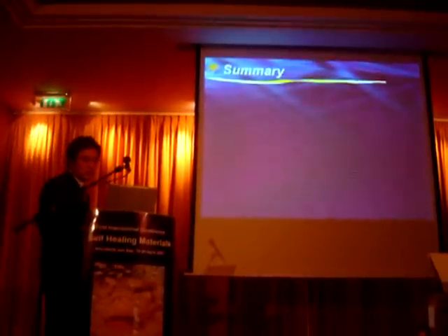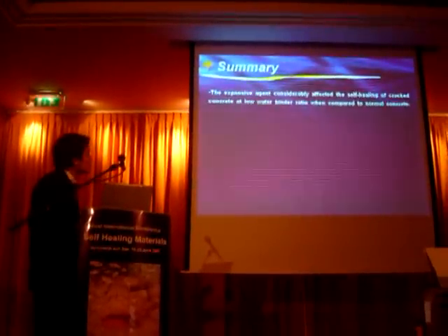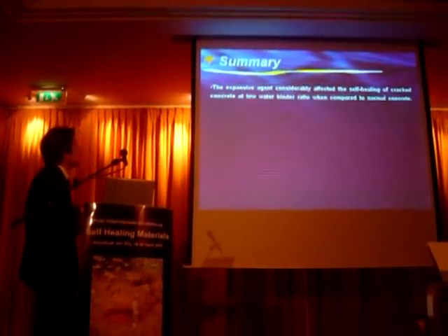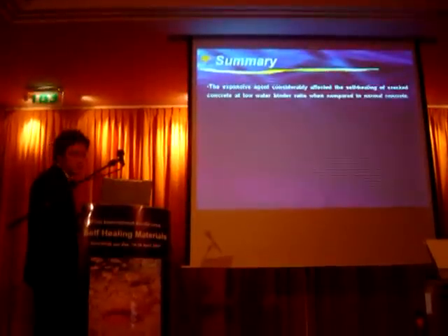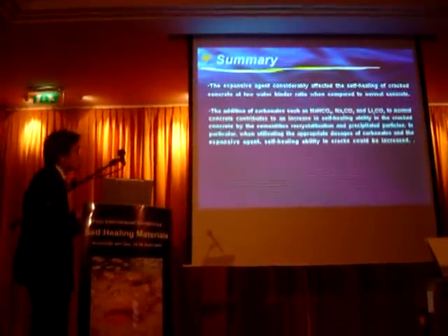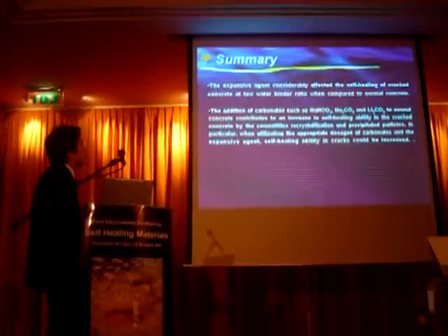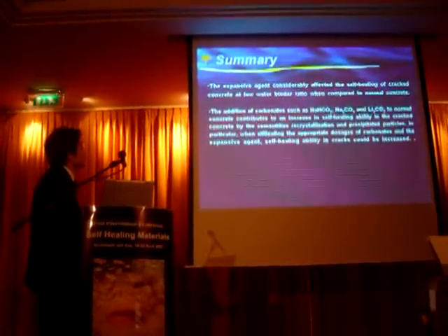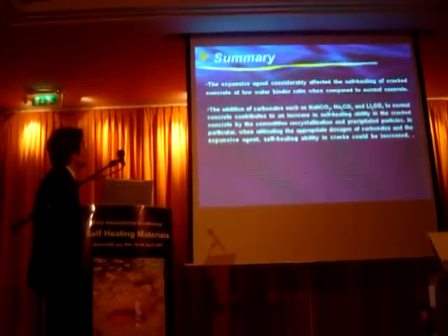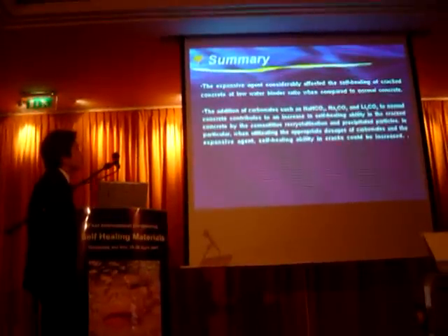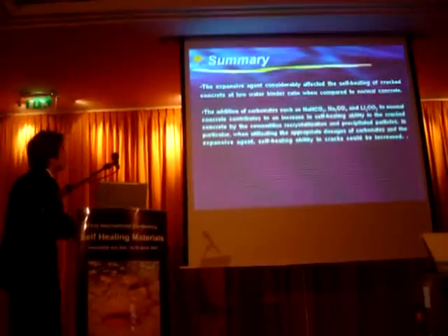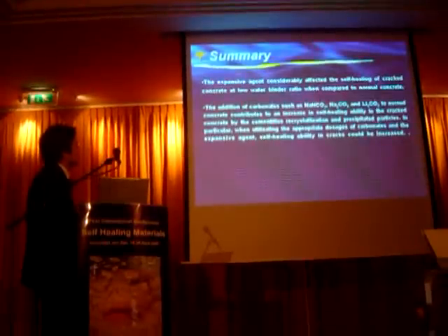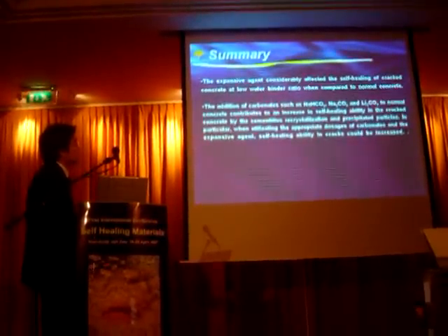So the summary of my talk is as follows. First, the expansive agent considerably affects the healing of cracked concrete at low water-binder ratio when compared to normal concrete. Secondly, the addition of carbonates, such as sodium hydroxycarbonate, sodium carbonate and lithium carbonate, to normal concrete contributes to the increase in healing ability in cracked concrete by cementitious recrystallization and precipitation particles. In particular, when utilizing appropriate doses of the carbonate and the expansive agent, healing abilities in cracks could be increased.